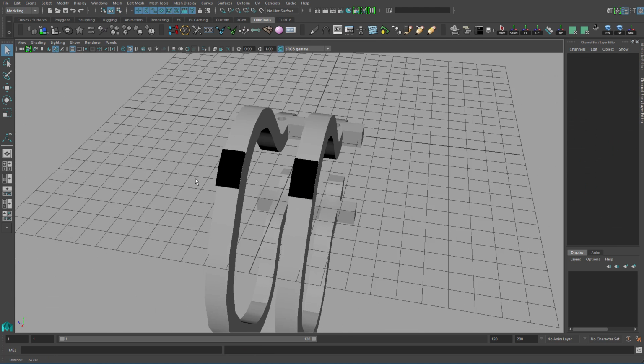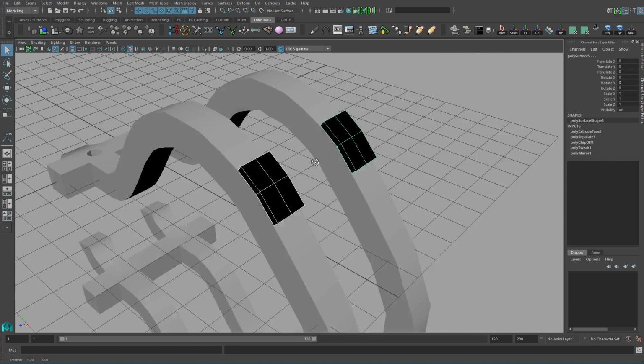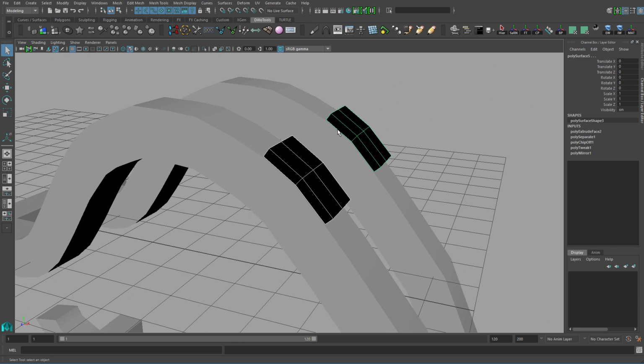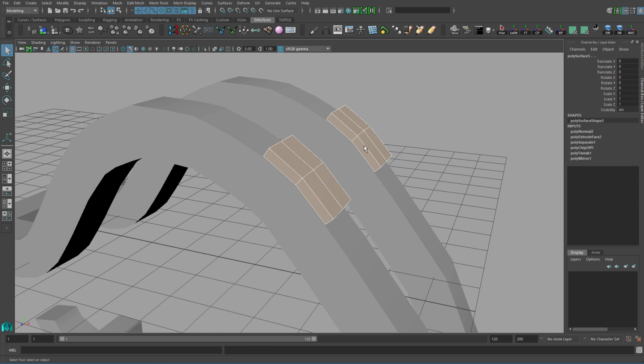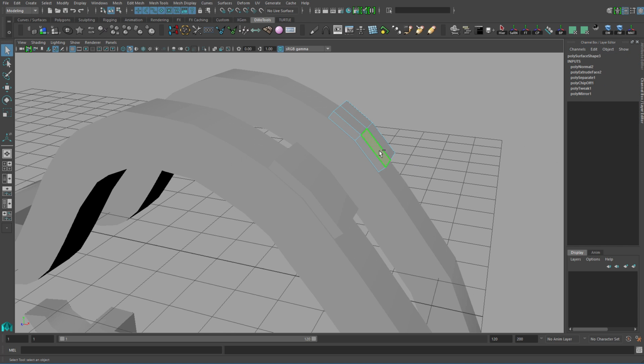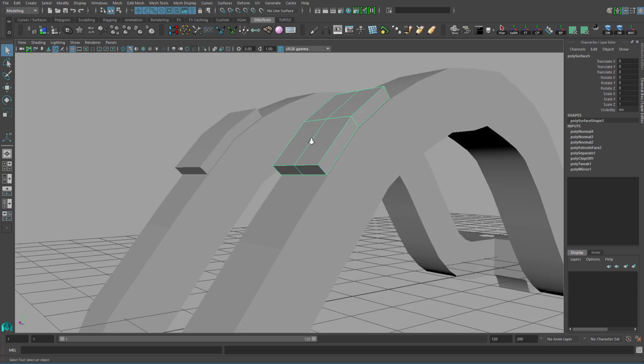Like that. And you see it turns out to be black. That's because their normal is reversed. To reverse the normal, you can go to Modeling, Mesh Display, and Reverse. The shortcut for this will be you have to go to Face Mode and grab one of the faces, Shift and right mouse button, Face Normal, reverse the propagate. That reverses the entire consistent portion of this geometry.